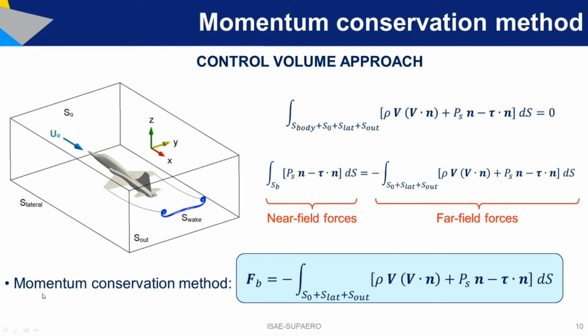So the momentum conservation equation basically allows us to establish the force acting upon a body. That's basically the near-field method, given by this general expression, the momentum conservation equation applied to the external surfaces acting upon a body. The problem of the formulation as it is that it's not that practical for CFD applications. It's absolutely prohibitive for wind tunnel applications, and let me explain you why.